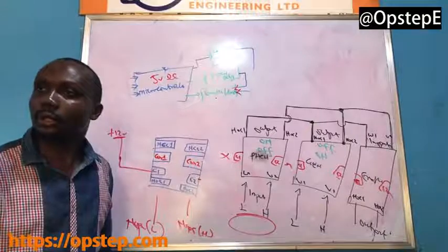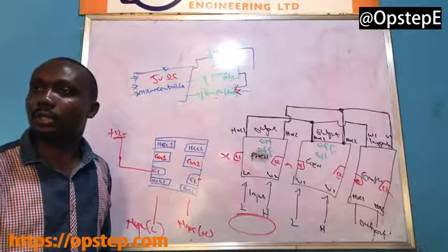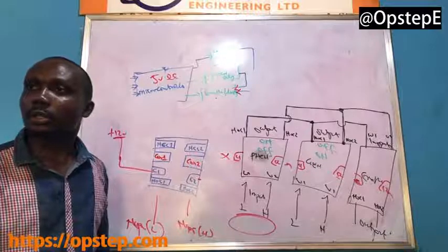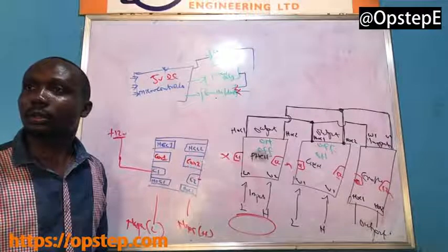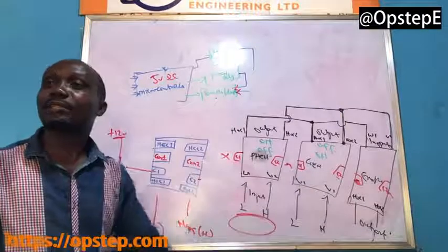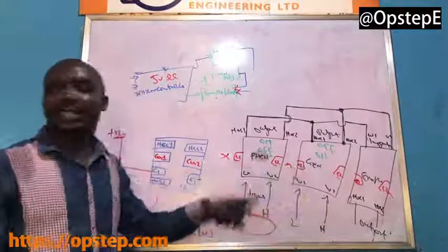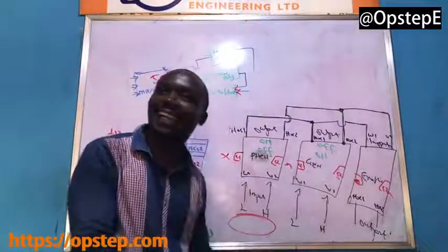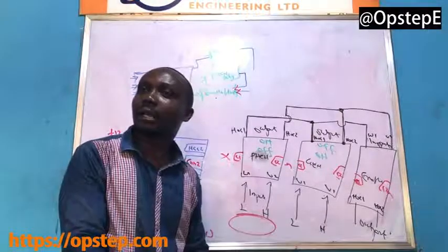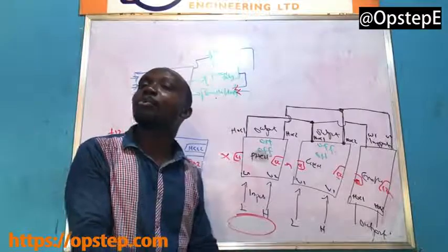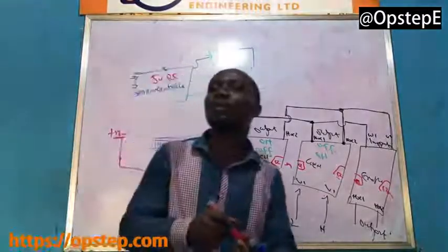Okay. And I want to switch to generator. So now I've turned on the gen, but I'm yet to allow it flowing. So do I have to instruct the PCN contact coil to go off first before I now instruct, or immediately I tell the gen contact to come on? That's what I've been saying. You're saying that in automatic mode, both of them can't be on, which I understand. In manual mode too, that's why I said the system is foolproof.